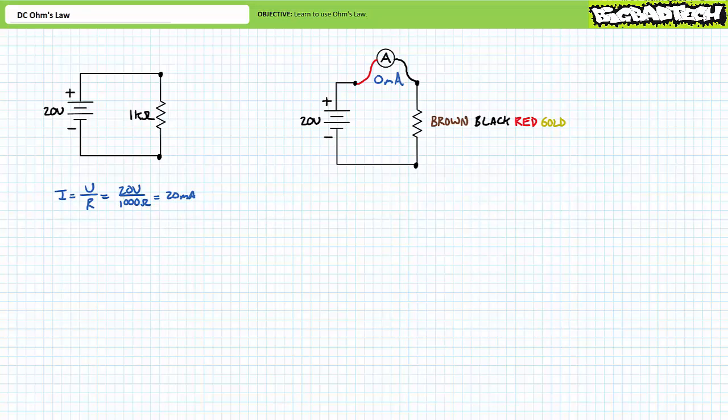First, ask yourself, did you turn the source on? You'd be surprised how many troubleshooting scenarios are resolved simply by pressing the large button that says on. I've done this myself more than I'd like to admit. What if the source was on, and you still observe no voltage drop across the resistor, nor any current through it? Ask yourself, what is stopping current? Perhaps something with an infinite resistance. I previously assured you that it was in fact a 1 kilo ohm resistor.